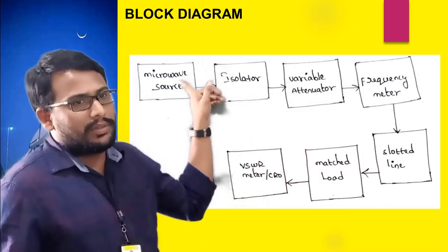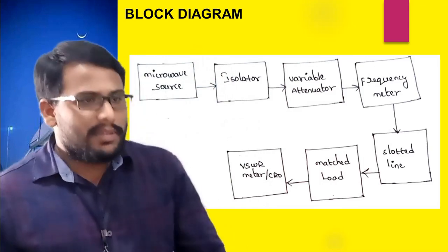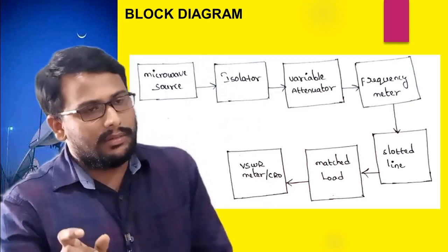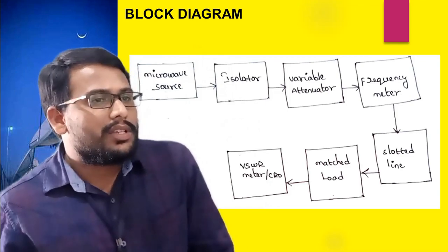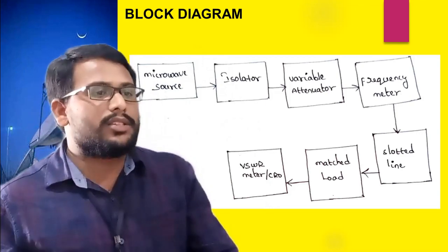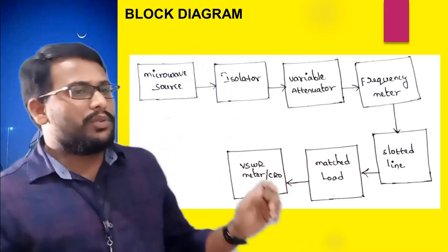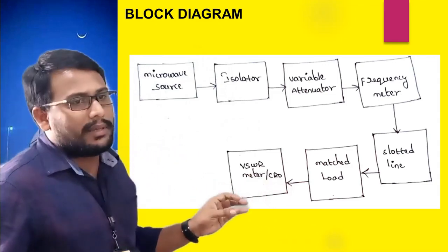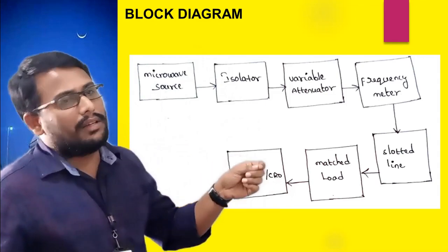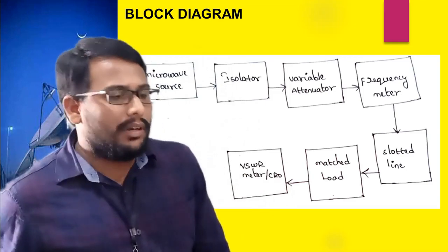Initially, there is a klystron power supply connected to the klystron mount. When you switch on the klystron power supply, which is a solid state regulated power supply, we apply a particular voltage to the klystron mount. And the klystron power supply incorporates different knobs.